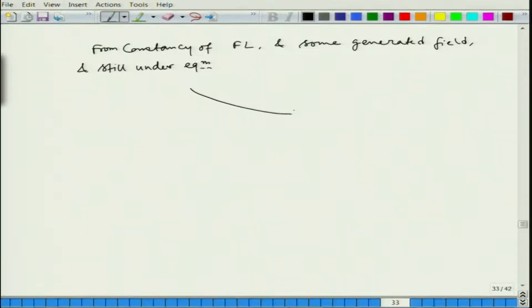So, let us say this is the change in potential for the conduction band, and this is the change in potential in the valence band, and we have seen that they will be parallel because they are measured under the same datum. And constancy of Fermi level says that throughout the material the Fermi level should stay the same. Okay. It cannot be different.